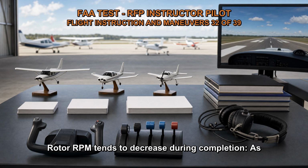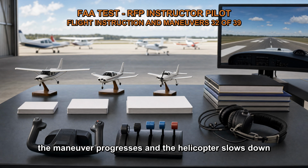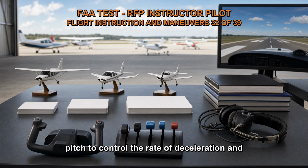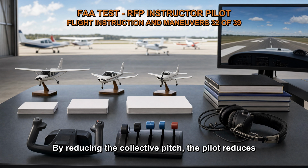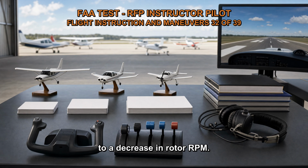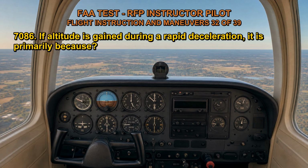Rotor RPM tends to decrease during completion. As the maneuver progresses and the helicopter slows down further, the pilot will gradually reduce the collective pitch to control the rate of deceleration and prevent an excessive decrease in rotor RPM. By reducing the collective pitch, the pilot reduces the lift generated by the rotor blades, leading to a decrease in rotor RPM.